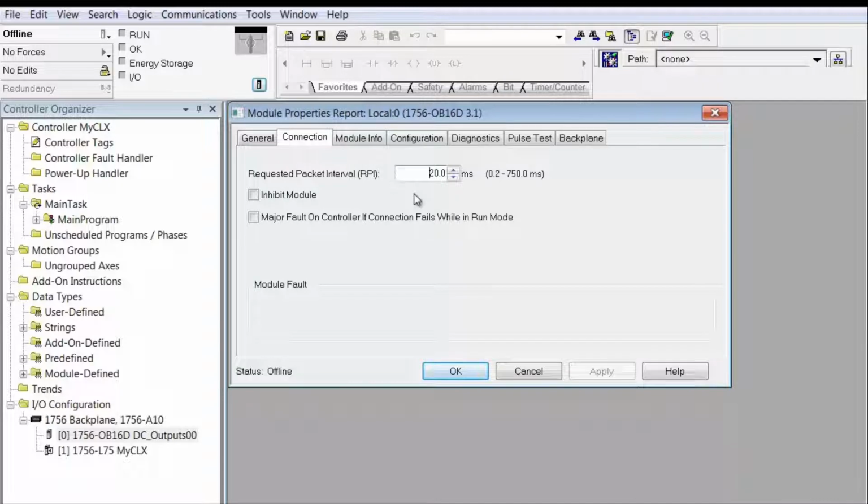The processor, by way of a control bus, would activate one slot, and then it would either push data into it or pull data out of it while the slot was activated. It was all electronic switching. There was no communications on an active backplane. This is a passive backplane. Everybody on the backplane communicates.